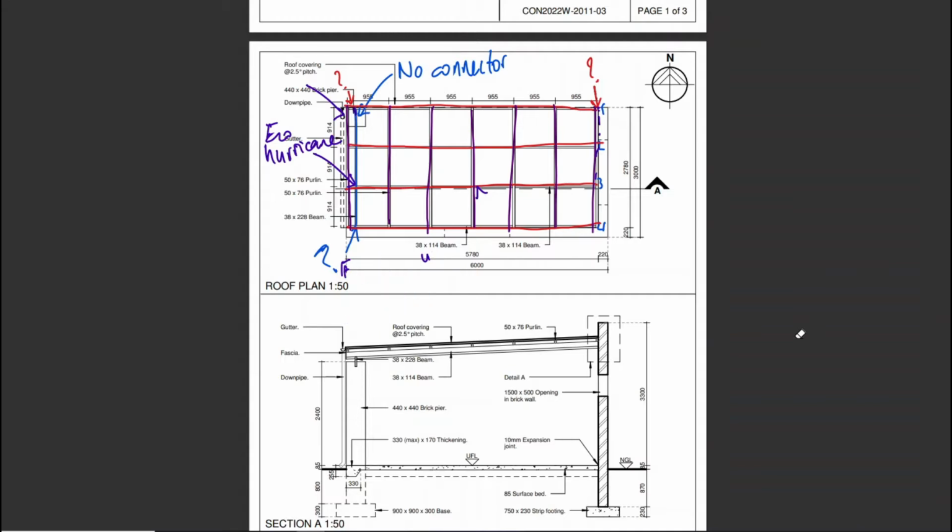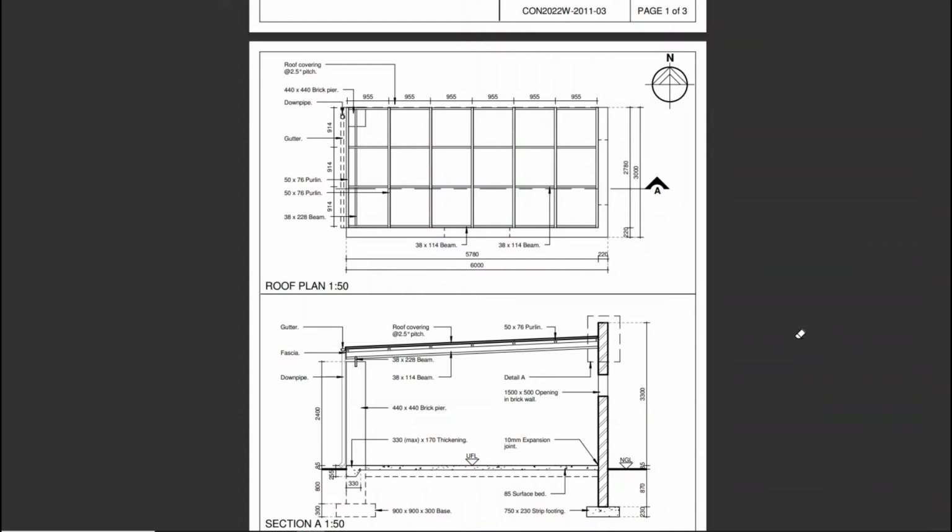If you want to research that yourself, you can. They're just nails that have a texture along the pointed end that penetrates the wood. And this texture adds to the frictional force between the timbers holding them together. So it's sort of like this, and then it's ridged. That's what a serrated nail looks like. You check it out. It's pretty interesting. At least I think so.